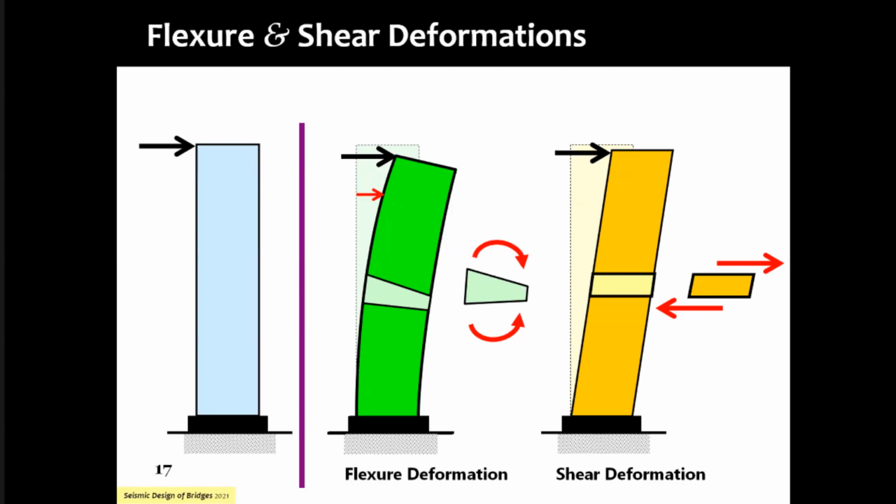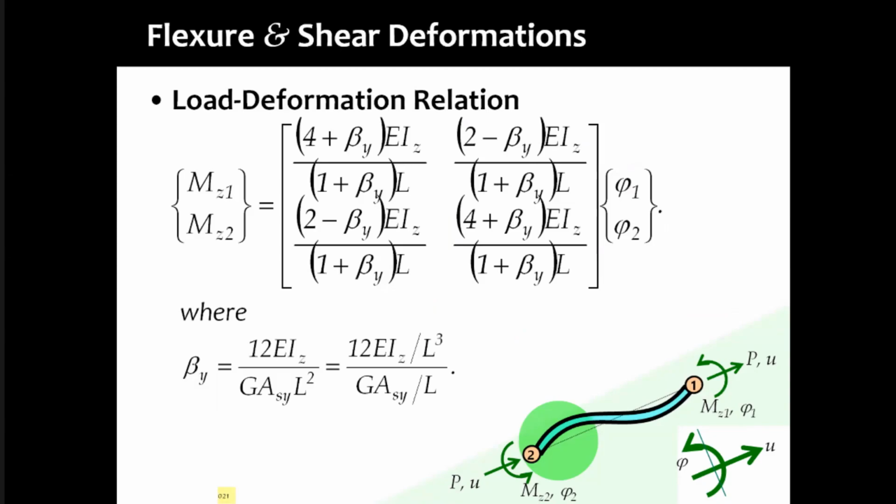If you bring in the shear deformation parameter, which is the ratio of the lateral translation stiffness in bending versus lateral translation stiffness in shear, you will notice that your 4224 classical matrix will not stand, and it can be a radically different number, so the bending moment values and shear force values will be radically different. So you have to switch on the shear deformation parameter, otherwise you are not making a good estimate of the actual behavioral characteristics of the members.